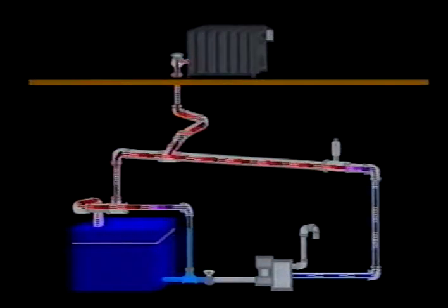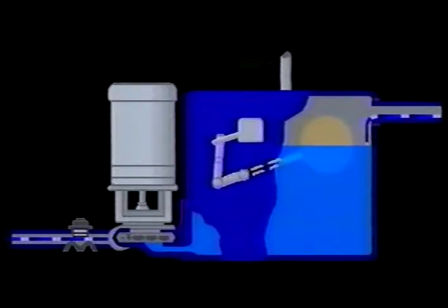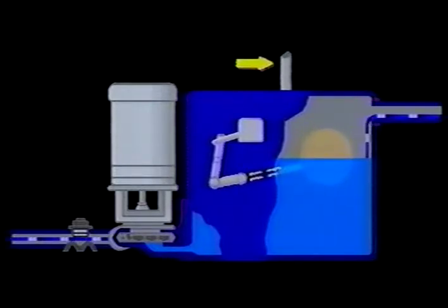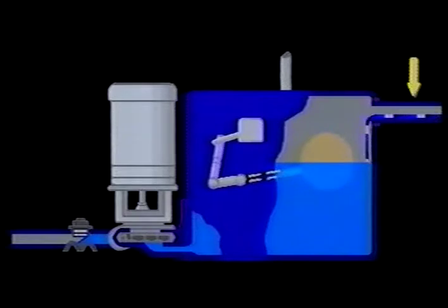On some semi-commercial installations, the use of a boiler with a condensate tank, feed pump, and a low water cutoff and pump control might be used. The receiver tank consists of a reservoir with a vent line, water sealed and open to the atmosphere, into which the return line discharges its condensate.